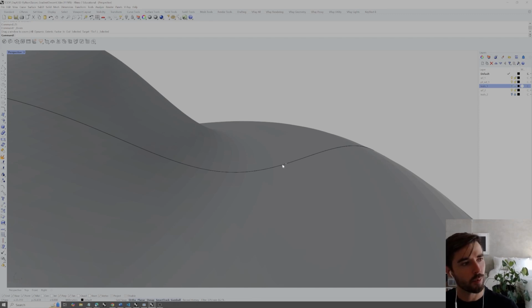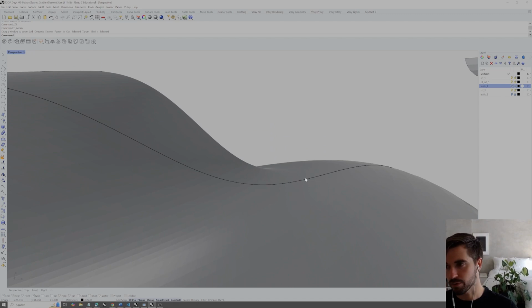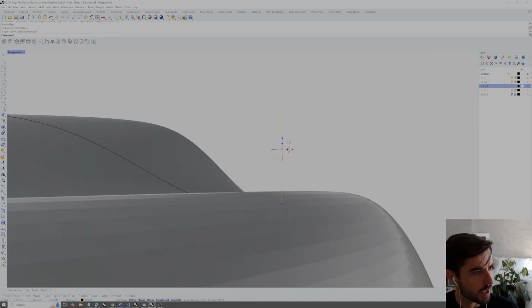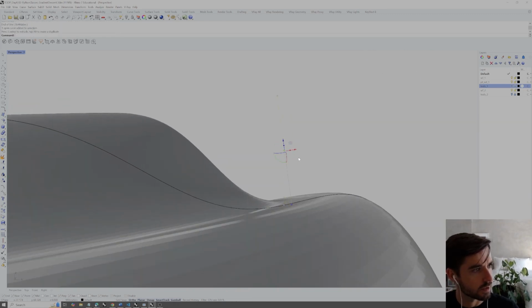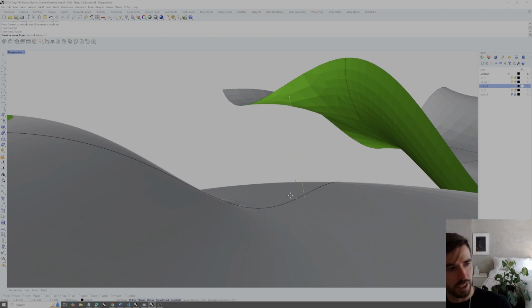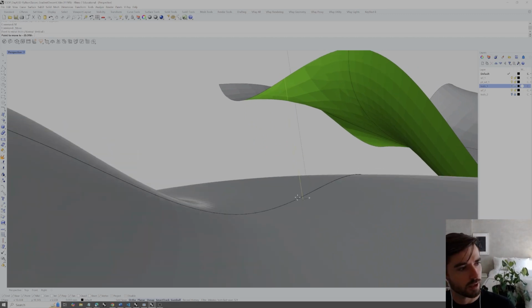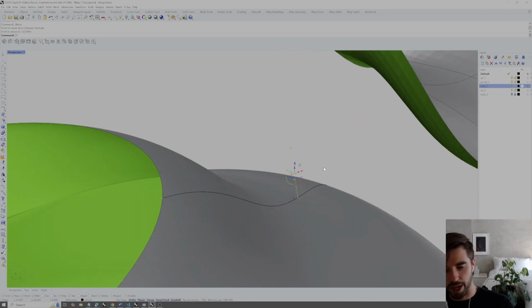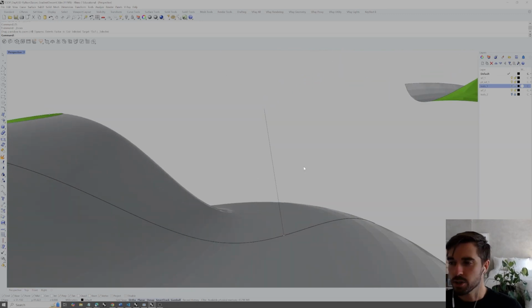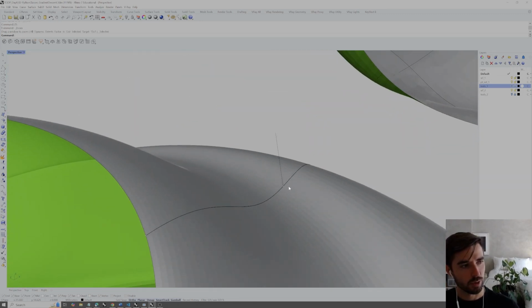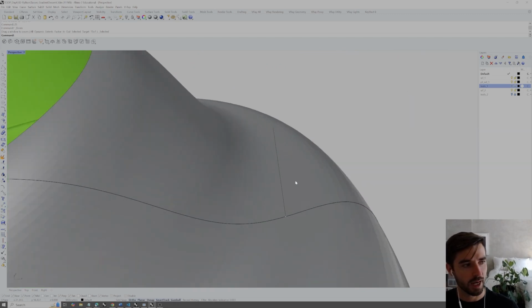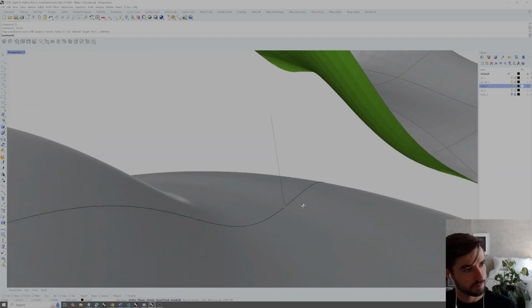We can get the normal, which is perpendicular to the surface at that point. So if we just draw, right now I'll draw a vertical vector, and maybe we can rotate this slightly because it looks like it's slightly tilted. So we'll do that rotation. And let's say that this is the approximation, at least, for that particular normal. So what is a normal? It is the perpendicular vector to a given face. Now, we can get that, again, by finding that closest point parameter, or closest parameter on the surface, using that parameter to get that normal.